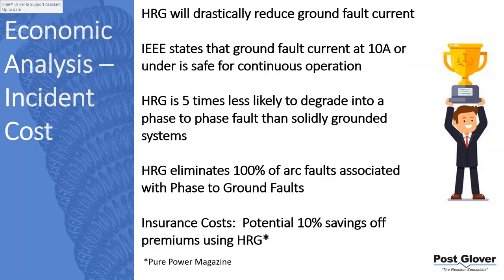I would explore with my insurance company and see if that is offered. I can't say that all insurance companies are aware of this idea, but of the few that are, to be honest with you, I don't know for sure how many at this point. This was done a few years ago in terms of this article, but it's a safer system. So it makes sense to get potential savings off of your insurance. If you're an engineer, I would definitely use that as a potential selling point for a high resistance ground system. If you're talking about premiums, a 10% saving is a lot of money.